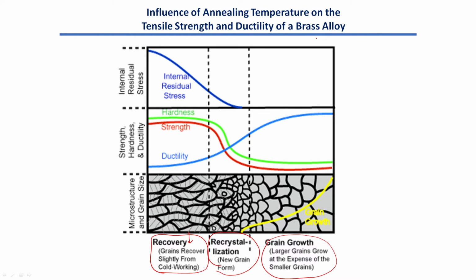As you know, if you deform a material, you create a lot of defects, and these defects actually are the primary agent for plastic deformation. And therefore, initially if you deform any material, let us say you take a piece of aluminum and start hammering, what will it do? It will create a lot of defects or dislocations basically, especially in the case of FCC aluminum, and these dislocations will not find enough time to arrange themselves properly. They will be haphazardly arranged in the material, and that increases the energy due to deformation. It will increase quite a lot.